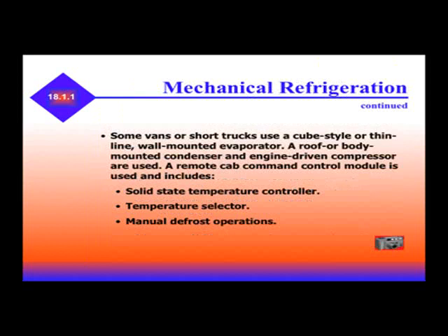Some vans or short trucks use a cube-style or thin-line wall-mounted evaporator. A roof or body-mounted condenser and an engine-driven compressor are used. A remote cab command control is used and includes a solid-state temperature controller, temperature selector, and manual defrost operations.